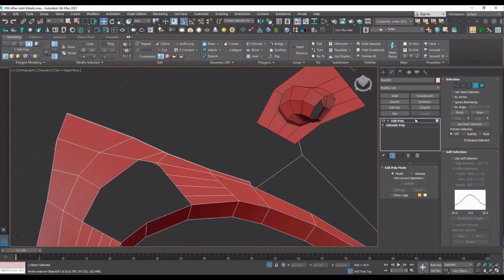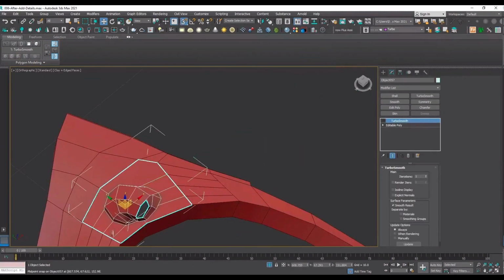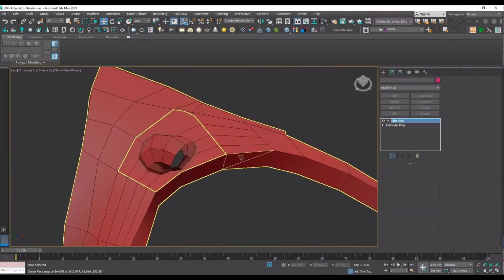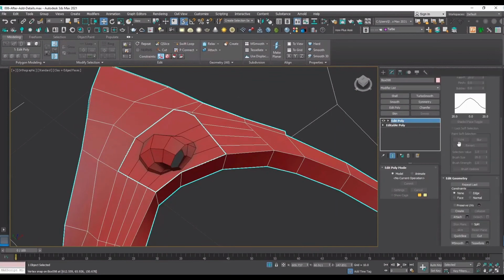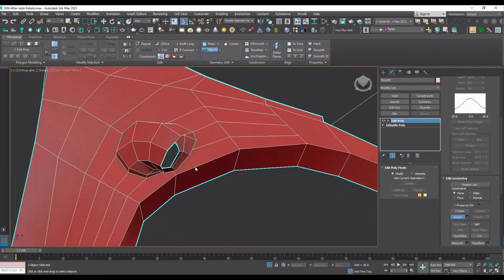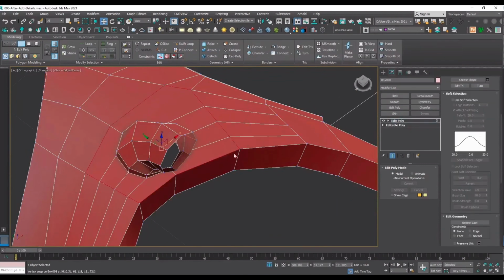And now we can just select those same faces and delete them and pick up this geometry and just snap it to the place. And make sure that you attach the base mesh to the detail and not vice versa, otherwise it will just exit the instance mode.